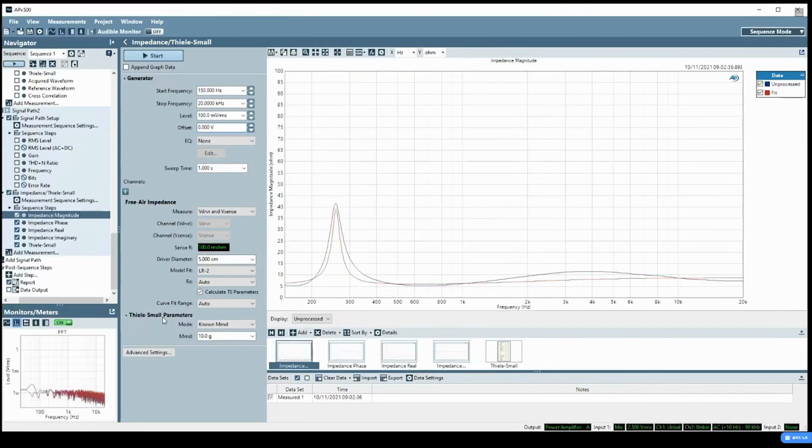No, rub and buzz has been there for a while, but that would be the rub and buzz peak ratio and crest factor that I explained with the high pass tracking filter, and then taking the residual from the high order harmonics and producing the peak ratio and the crest factor. The high order harmonic distortion, the rub and buzz loudness, and zone track are only available in 6.1 and later.